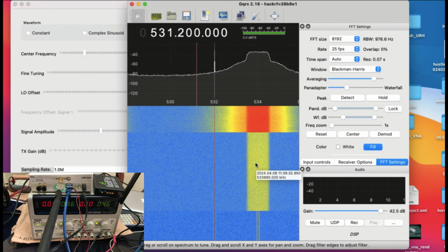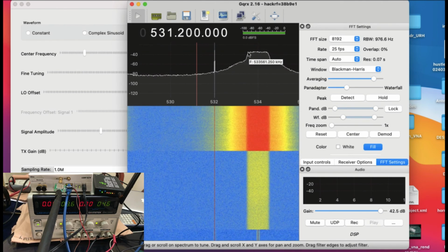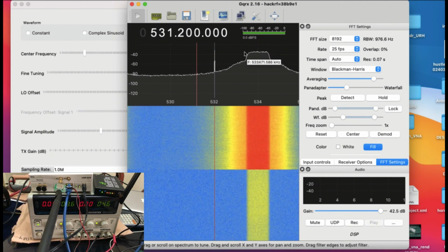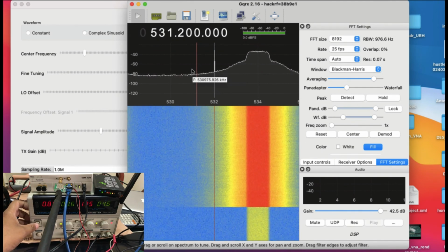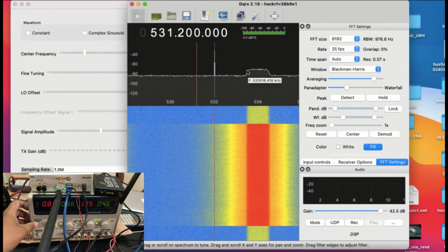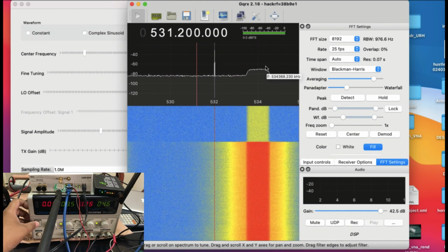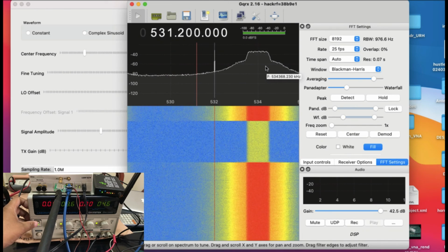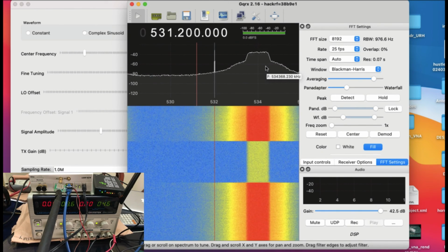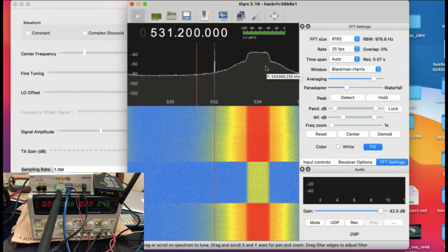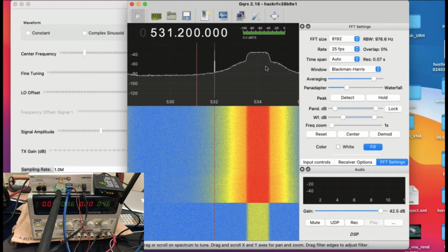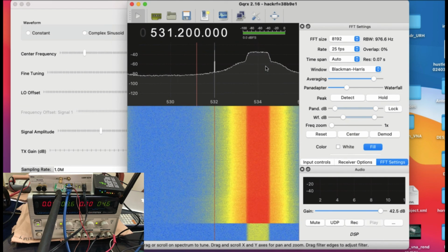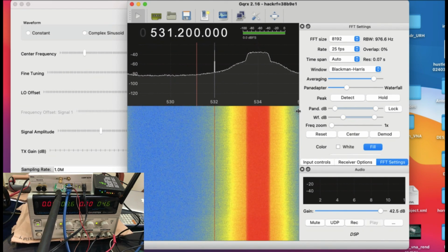So as it was green, and now all of a sudden you're getting an entire spectrum that is somewhere around -40, I would say even -30 dB. Your signal was somewhere around right here at -80, -70, and you're getting about a 20 dB jump when you're using an amplifier like this. So I can use this amplifier or a Gaussian noise source to actually cover a spectrum, or to do an effect of a noise, like a jamming effect. I can do that using this.